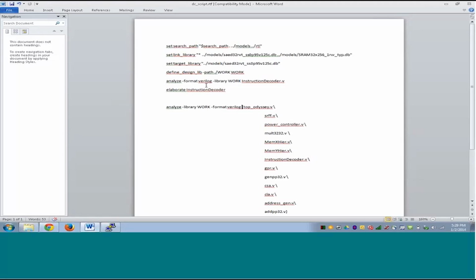So the focus of this lab was to make you comfortable with library and the elaborate report. So please focus on the elaborate report. Read in different kind of RTL files. See what the elaborate report contains. I'll focus on the compile command of this design. We'll talk about the design constraints, the environment constraints, how to set them, and then how to synthesize the design. Thank you.